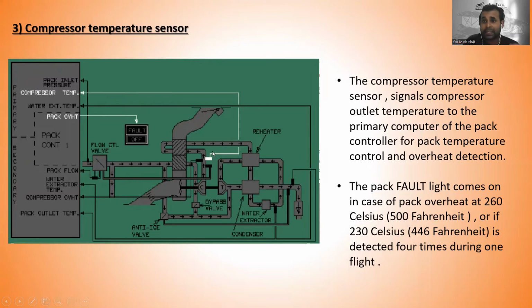So the compressor temperature sensor signals compressor outlet temperature to the primary computer of the pack controller for temperature control, and also for overheat detection, right?